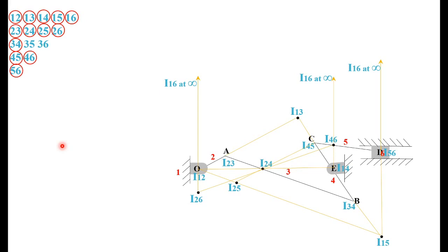Then next you take 2 3 5. If we take 2 3 5, the centers in 2 3 5 are 2 3, 3 5 and 2 5. So 2 3 is located, 2 5 also located. Therefore we can use that combination also for locating 3 5. Now you join 1 3 and 1 5 and also 2 3 and 2 5. So 1 3 is this point and 1 5 is this point. Joining 1 3, this is already a line, you can extend it in both directions.